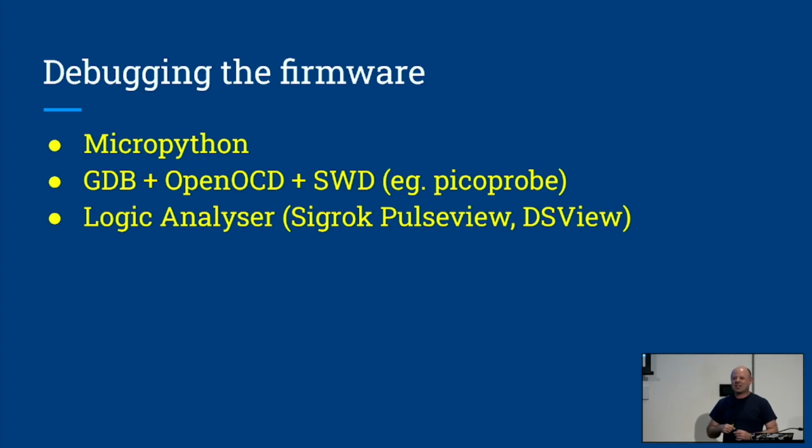Unfortunately, the tooling, at least what I'm using, a combination of VS Code, OpenOCD and GDB, basically crashes as soon as you add a 5th one. It doesn't say, warning, we can't support any more. It just crashes. So I've learned to keep a very close eye on how many breakpoints I have when I'm debugging, and it's super, super annoying at times to be limited to 4, but at least it's better than 0.